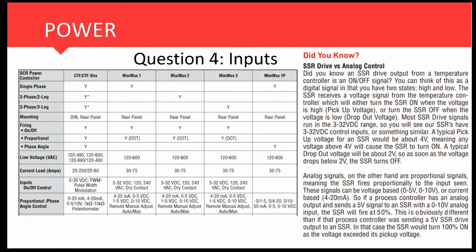And that's just what we've set as a company standard on our literature. The customer's numbers might be a little bit different, but it'll still be okay. For the analog control, we talked about 0 to 20 milliamps, 4 to 20 milliamps, all that kind of stuff. If a customer tells you any sort of analog range, you want to make sure that it does match exactly. So again, with the SSR drive, numbers don't need to match exactly, but for proportional analog type of stuff, they do.